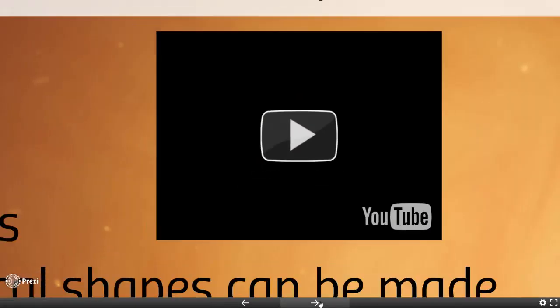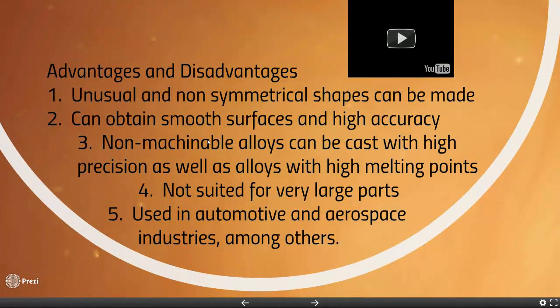So let's move on and look at some of the advantages and disadvantages of the lost wax process, or investment casting. So advantages: you can have unusual and non-symmetrical shapes that can be made. It can obtain very, very smooth surfaces and high accuracy. And it can do this for non-machinable alloys.